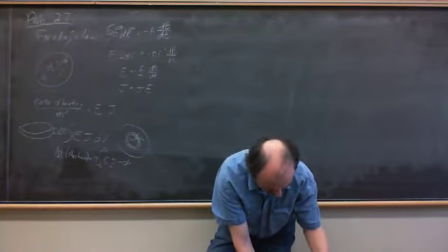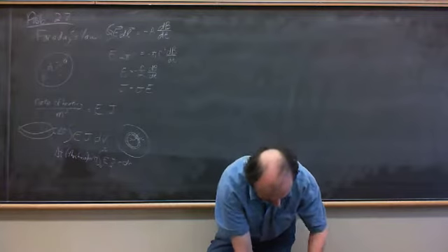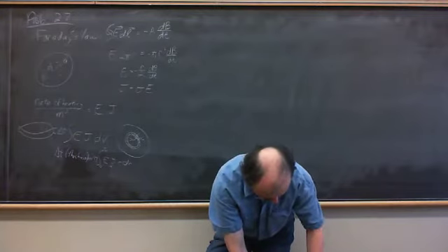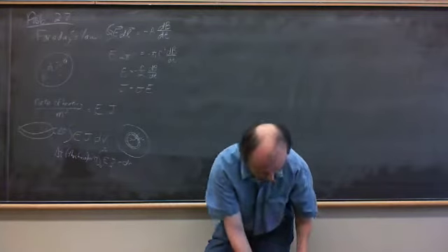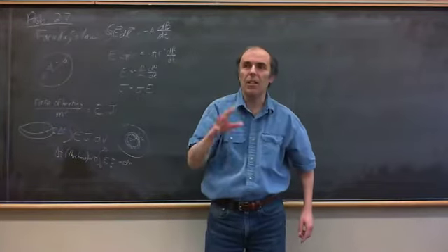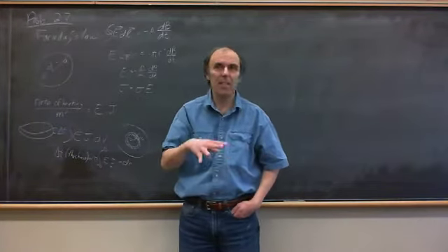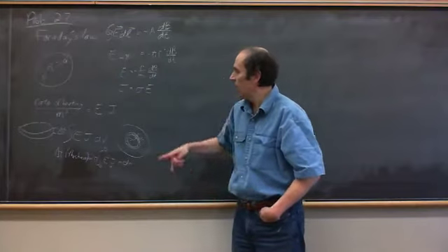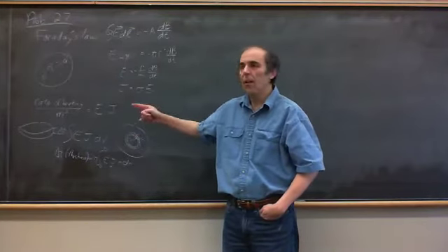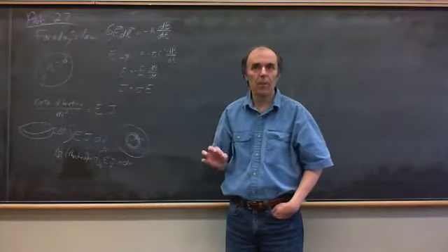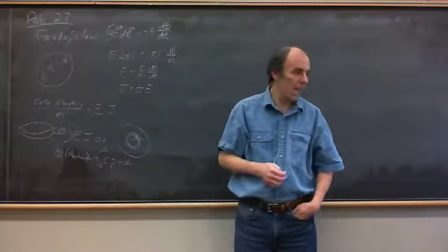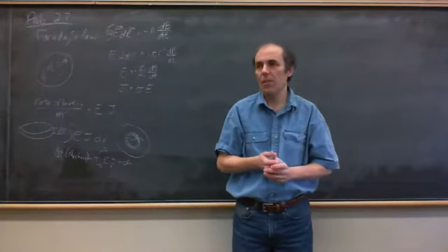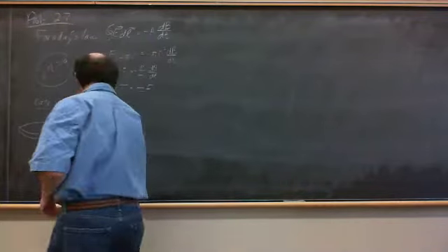So you're given some information so you can calculate the heat capacity of the electrode, which involves the specific heat per unit mass, and then you get the mass of the electrode, which is the density times its volume. So you can calculate the temperature increase for each stimulus pulse. And that is your final answer. You're asked to find how much this electrode heats up.